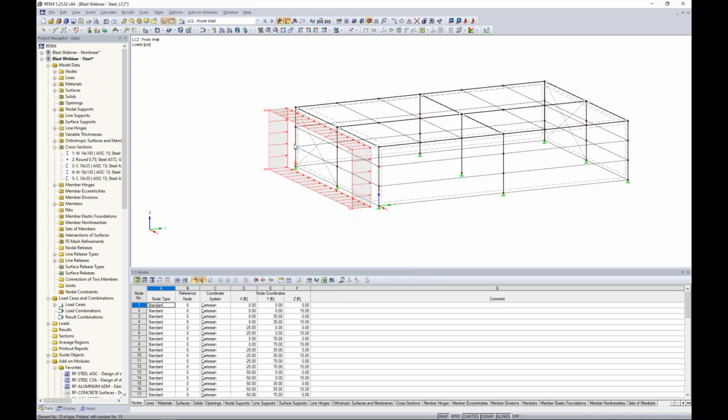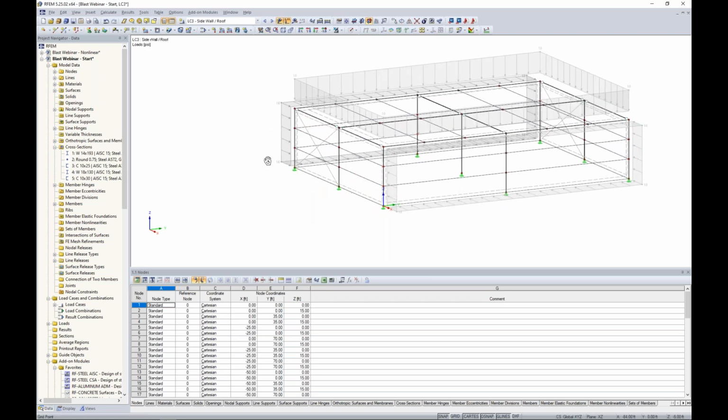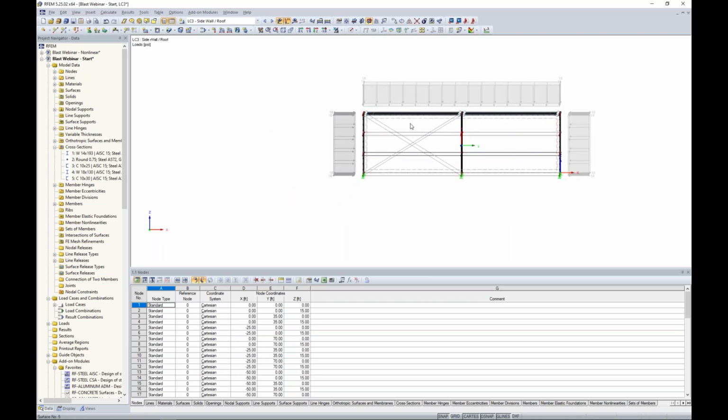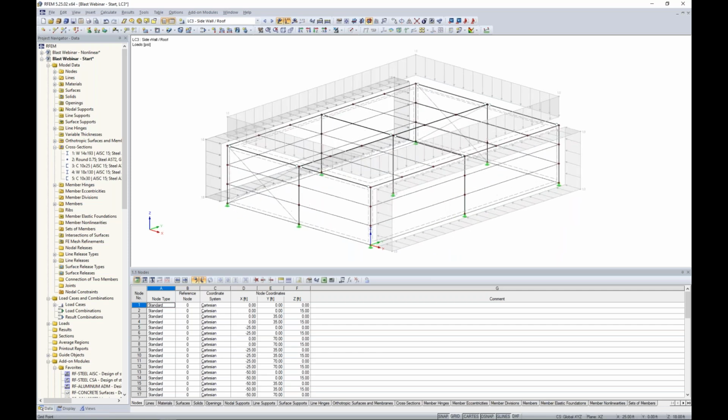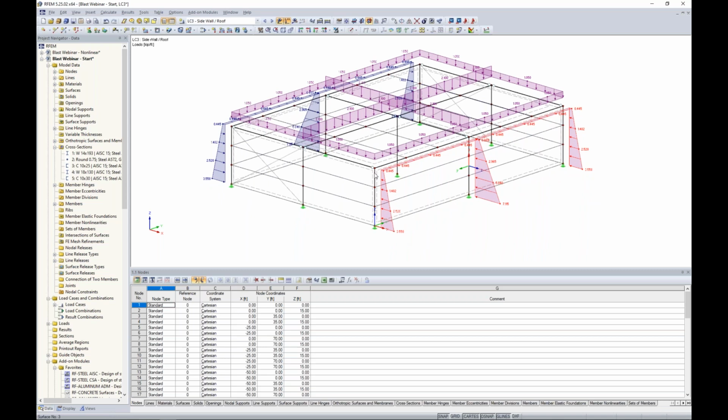In a similar fashion, if we take a look at load case 3 here, we have area loads on the sidewalls as well as area loads on the roof. And once again, all of the magnitudes are 1 psi. If I right click and I display separately, you'll notice that I applied them to those main frame elements. I did not apply them to any of the channel sections for the girts or the purlins. And again, I did not apply directly to the surface. I'm more interested in the structural response of these main elements included in our frames.